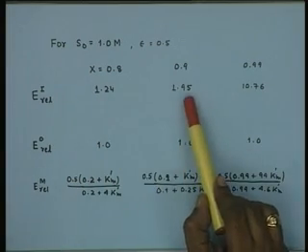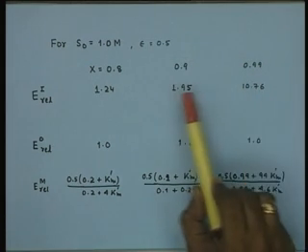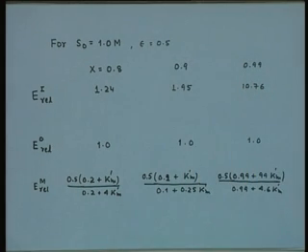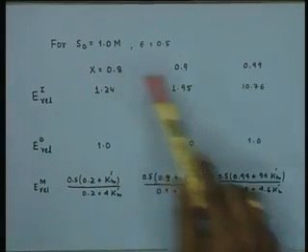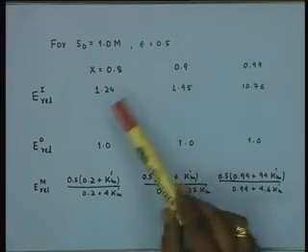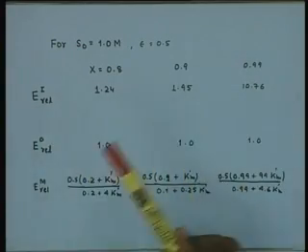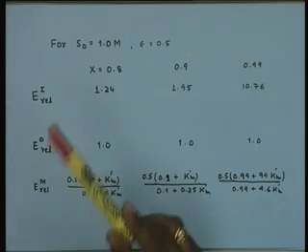almost about 1.5 times. But when you go from 0.9 to 0.99, you see the relative quantity of enzyme becomes more than 5 times, and it increases very significantly in the first order enzyme. And if you consider from 0.8 to 0.99, the ratio is still higher. The same relationship will also hold good for space time, the tau.